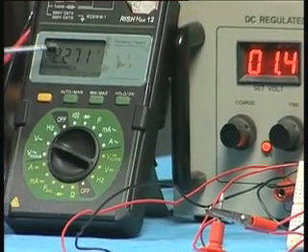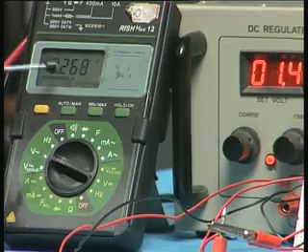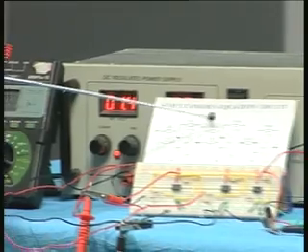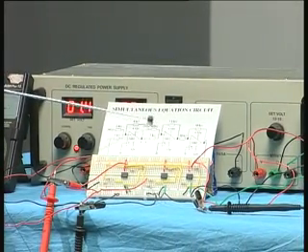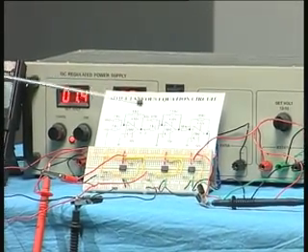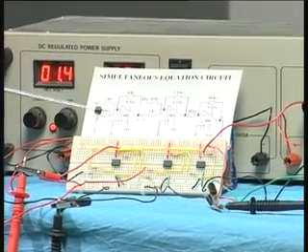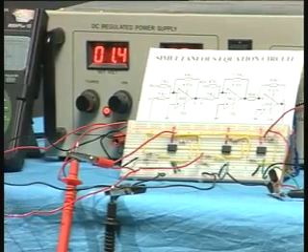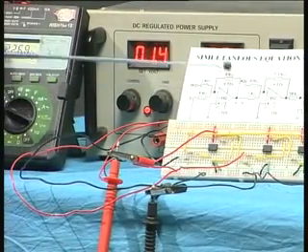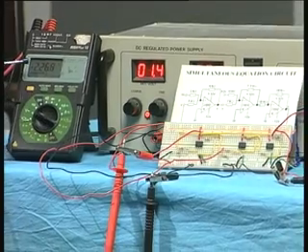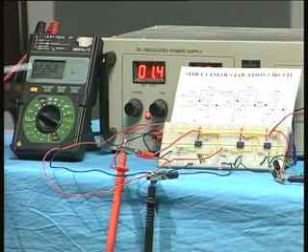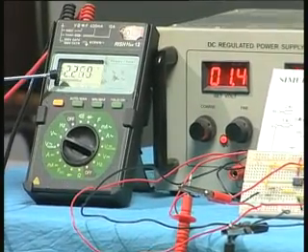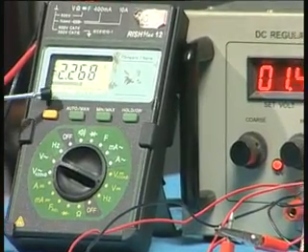There is a slight variation here. It should be precisely minus 2 volts. It is not, because I have not used very precise resistors here. For example, I have used 470 ohms instead of 500 ohms, and all these resistors will have some small variation because of the tolerance, and therefore there is some residual extra voltage that comes in here, minus 2.2. If I use very precise values of resistors at every point and measure, I will get a very precise value of minus 2 volts. I do not know whether you are able to see the minus sign here. It is minus 2.2 volts, right. This is minus 2.2 volts.